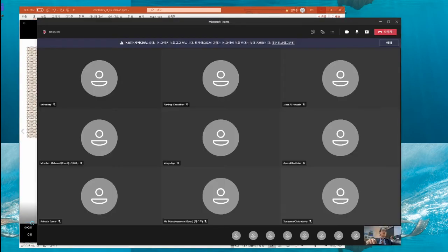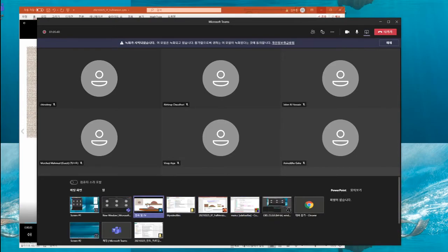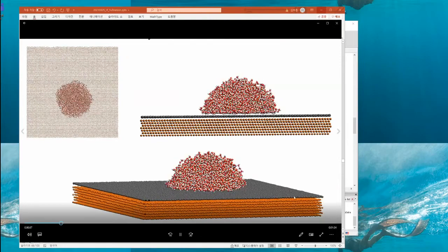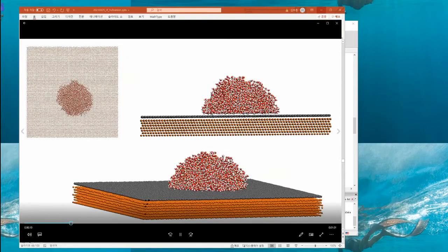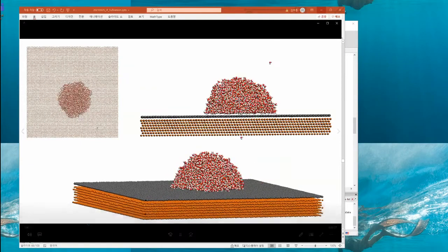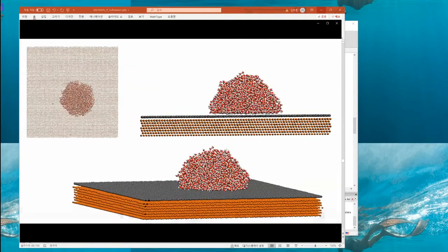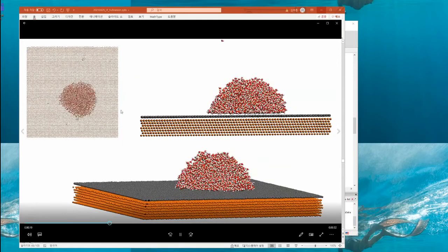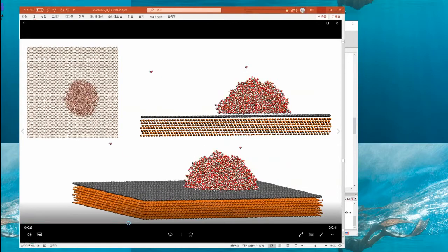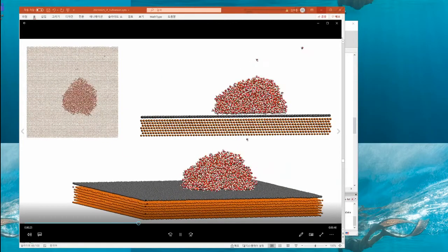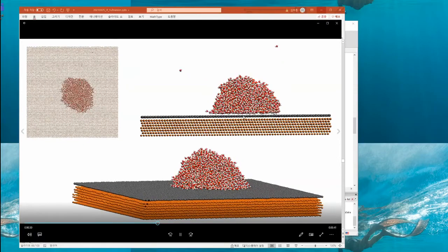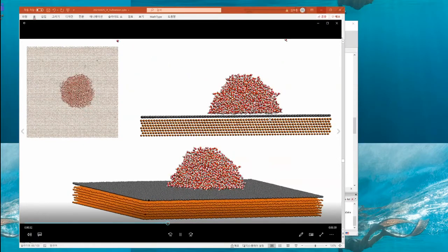All right, so I open that. Let me switch this to that one. Okay, so I have a copper and the graphene sheet, and I put a water droplet in there, and this is what a typical LAMMPS MD looks like. And we can add one graphene, two graphene, three graphene, and we could see how the contact angle changes. Starting with one graphene, it is likely a copper surface. But as I put more and more graphene in there, it behaves like the contact angle on graphite.